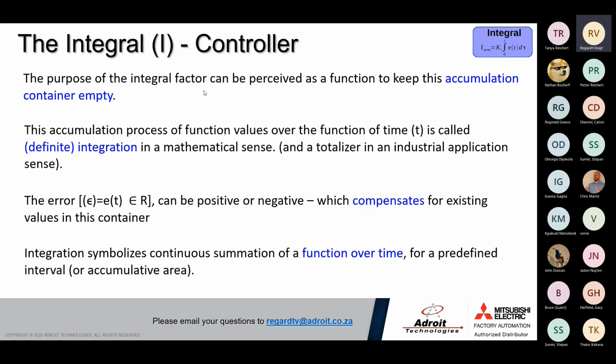The principle of operation of the I controller will be the definite integration over time. If you look at it from a mathematical sense, or from an industrial application sense, like PLC programming, it can best be compared to a totalizer. Okay, a totalizer that resets over time.